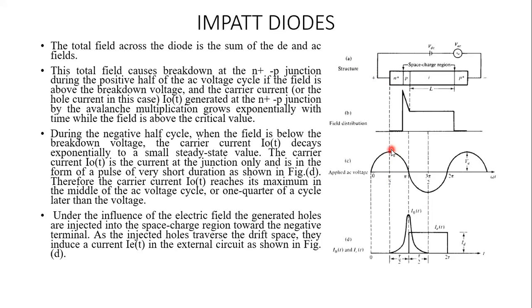So you can see that the process of charge building occurred at this positive peak, and a current is set in the negative region, where the AC voltage has decreased and the current has increased. This behavior is what sets a negative resistance.